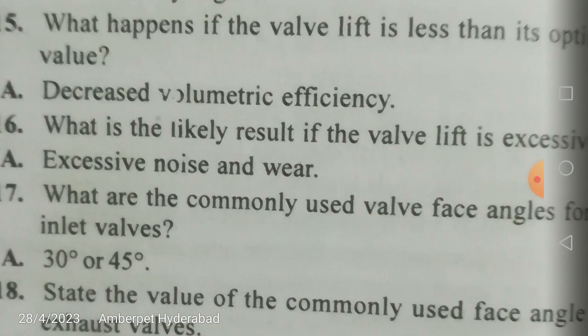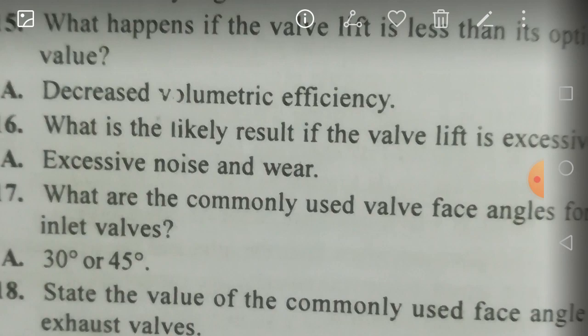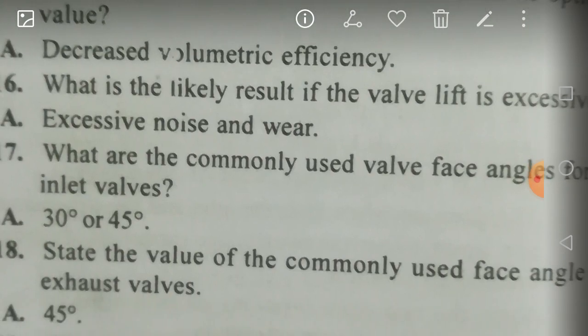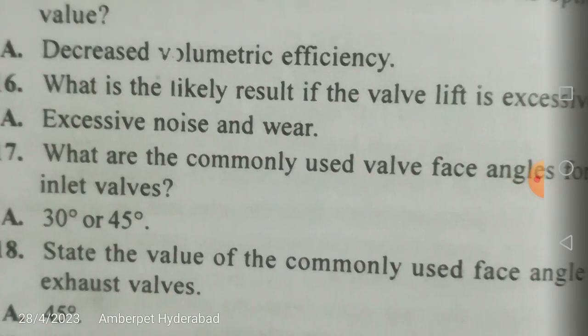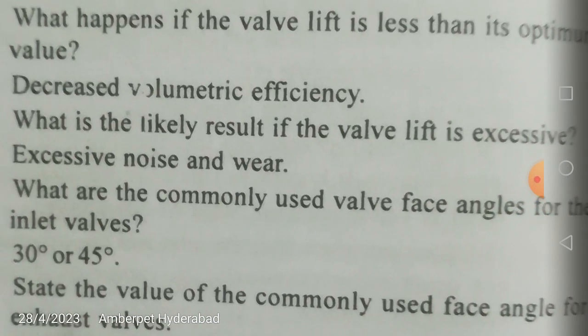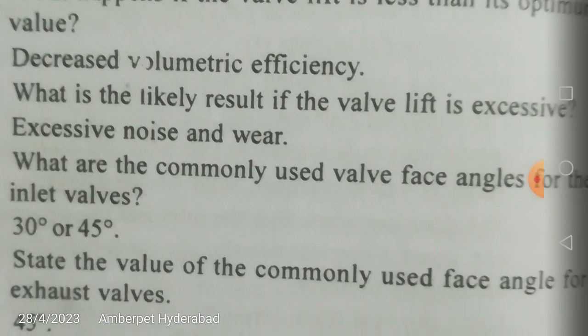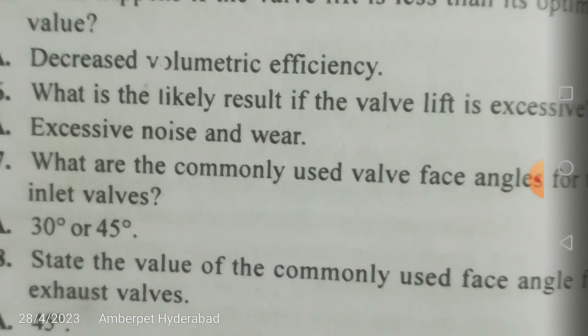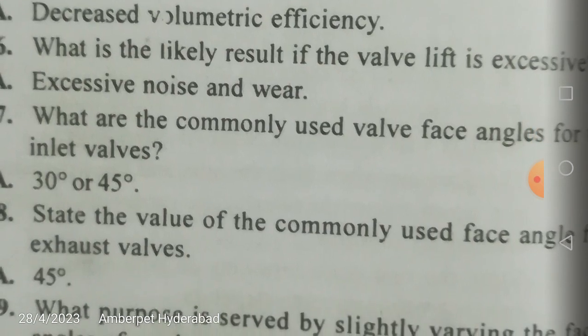Definitely it has to be more than 95% minimum. Please remember this. Now, what is the likely result if the valve lift is excessive? If it is less, it decreases volumetric efficiency, and if it is more, it causes excessive noise and wear. That's why it has to be kept optimum.